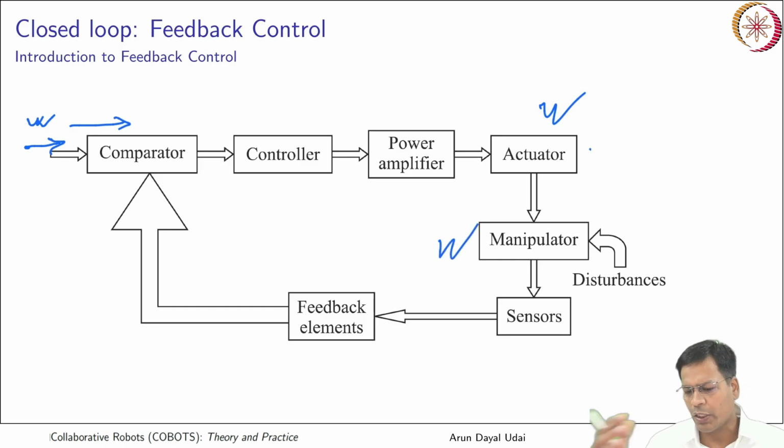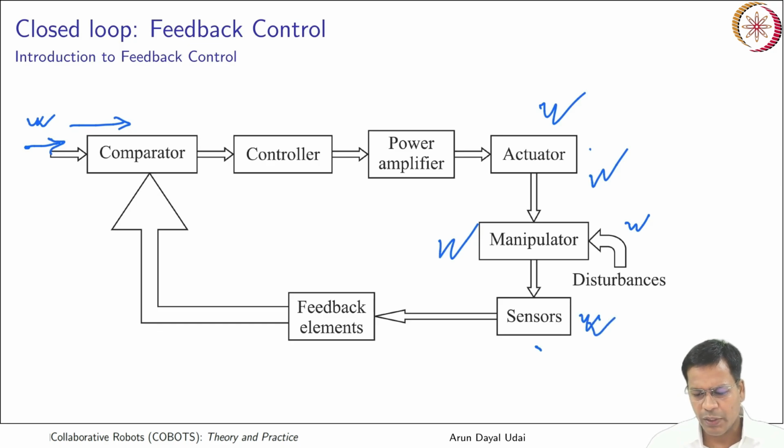Manipulator is basically your robot arm that takes in different kinds of disturbance due to payload, due to its supplementary load, due to the environmental disturbances, wires and etc. So those disturbances will come here. Finally, whatever torque you put over here through the current that you are putting, that goes as an output to the end effector. And at the joints you also have sensors. Those sensors give you the actual feedback of the joint position and joint velocity.